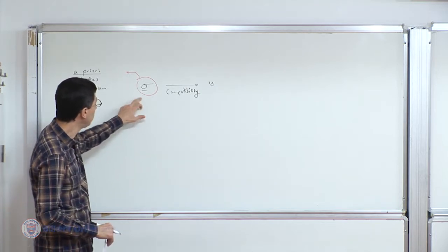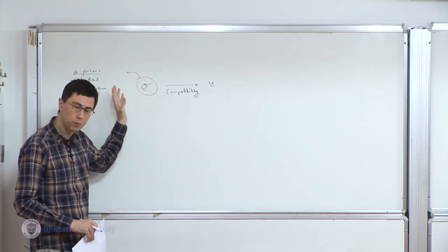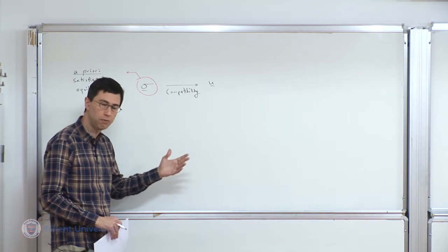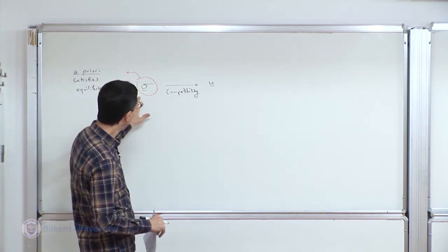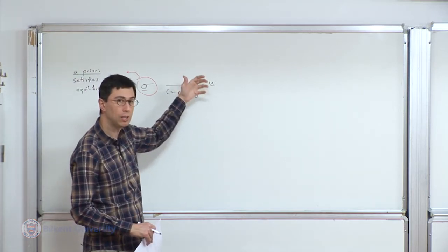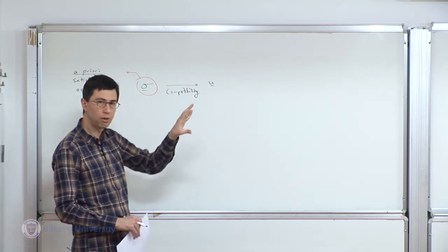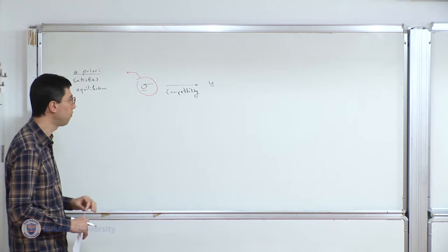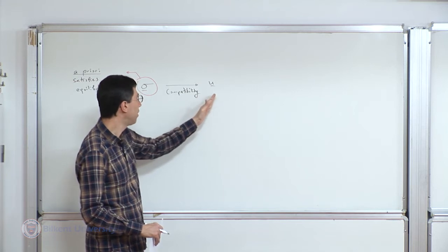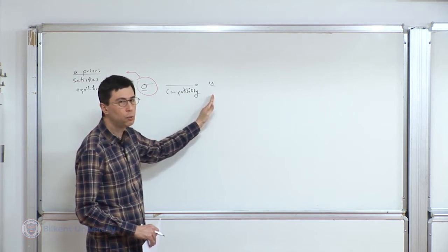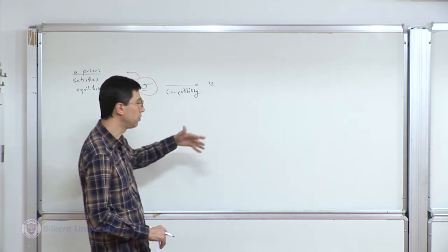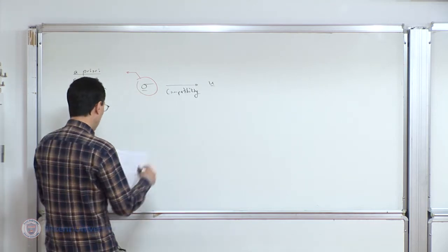In this case, we start with a form of the stress. Eventually, I'll show examples. We start with a form that is already simplified by looking at the symmetry of the problem, and that form already satisfies equilibrium. We're going to enforce compatibility, and that will allow us to restrict that form to the particular solution of the problem. Enforcing compatibility ensures that there is a displacement field, though it will be up to us whether or not we want to construct it. But once we enforce it, we know that there's a physical displacement field that causes that stress field. So this is the approach.